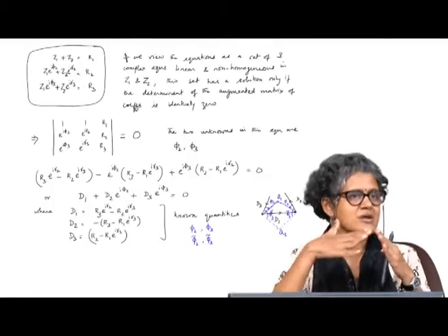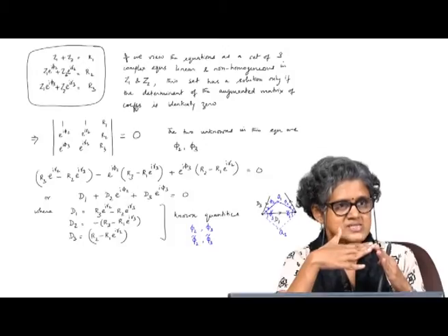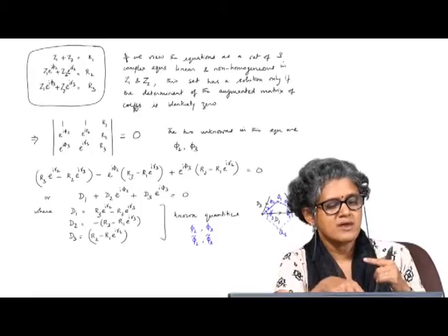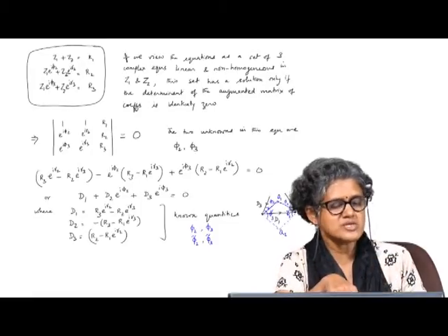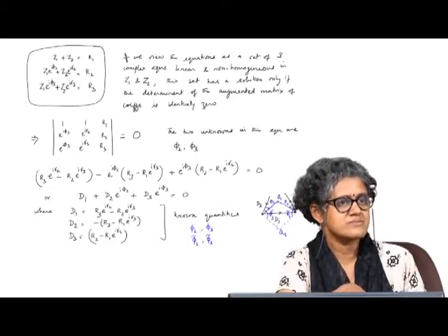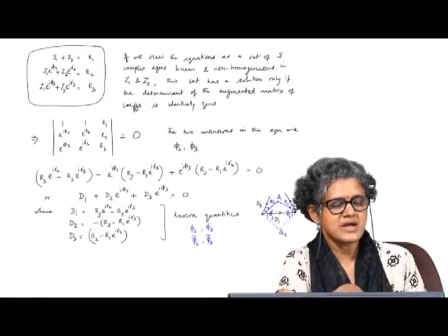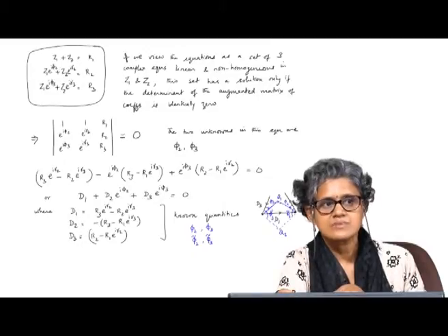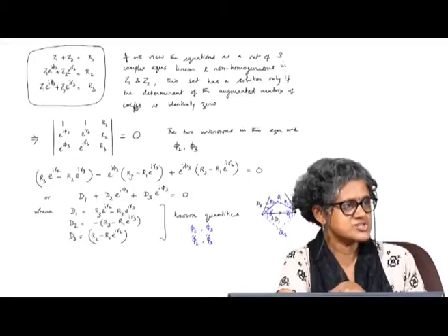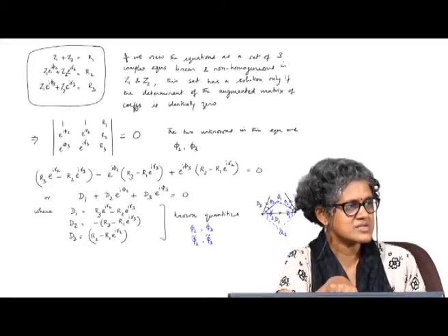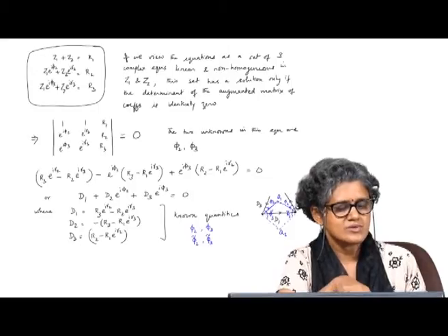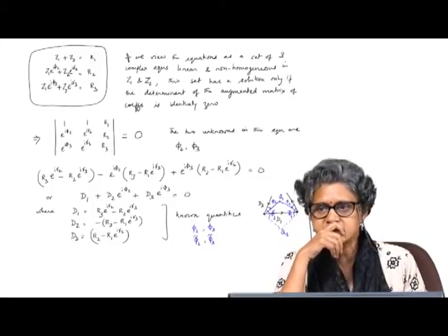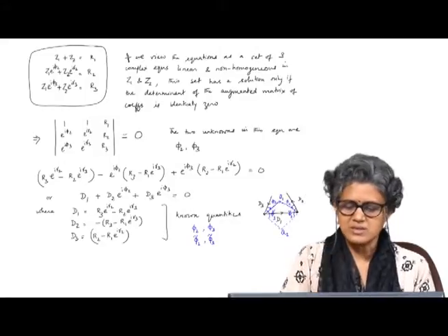This basically gives you an idea of what we are trying to do. We are trying to find the two intersections such that this compatibility equation will be solved. One of these, of course, if you look at the form of the equation itself, one solution becomes obvious. What is that? If phi 2 equal to gamma 2, phi 3 equal to gamma 3. That is the trivial solution which will satisfy this compatibility equation. So, you have one solution right there, because two columns of the determinant become equal, and your determinant is 0. So, that becomes the trivial solution.